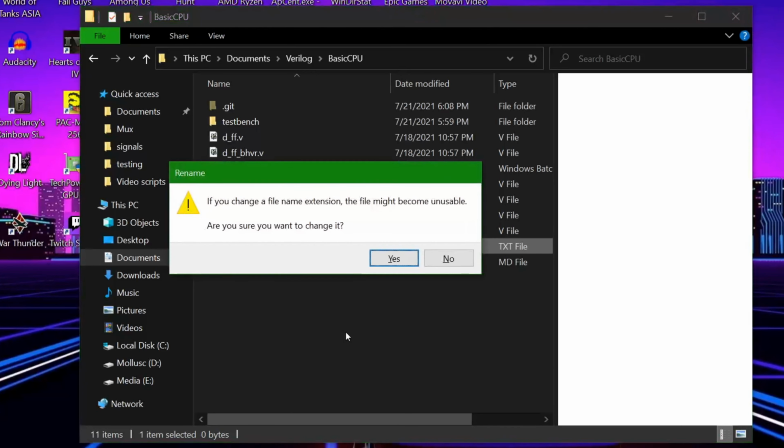I'll declare the inputs here. Data should of course be an in-out port. Here's the data int signal. It should be of type reg since we expect it to hold its value. Here's the reset condition.